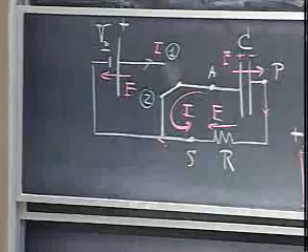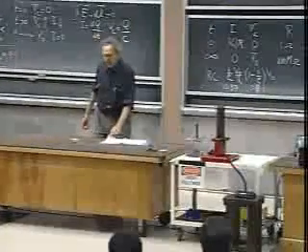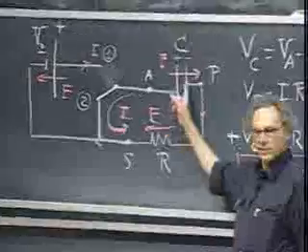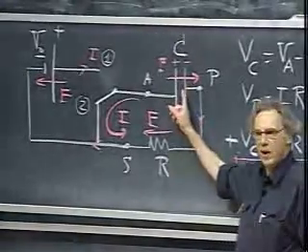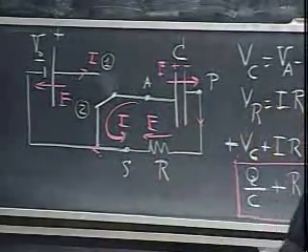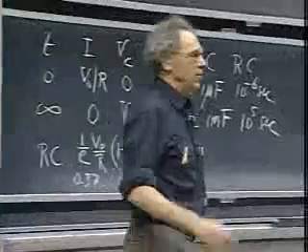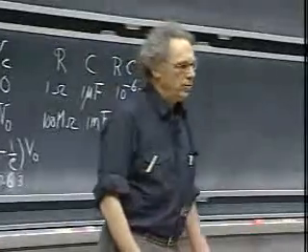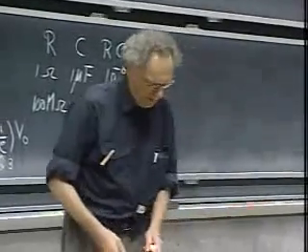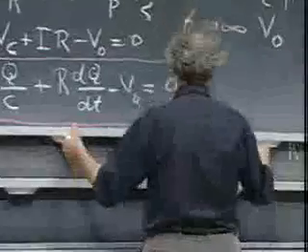And what is going to happen is the capacitor is discharging now, and the resistor will dissipate the energy that is in the capacitor. The 1/2 CV squared energy stored in the capacitor is going to be dissipated in the resistor in terms of I square R, in terms of heat. And if you wait long enough, the current will become 0. So it should be obvious what's going to happen.